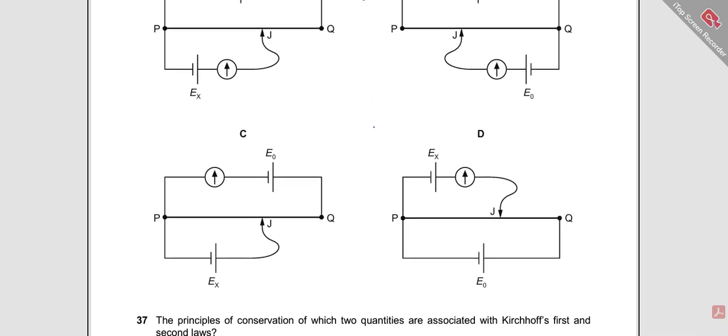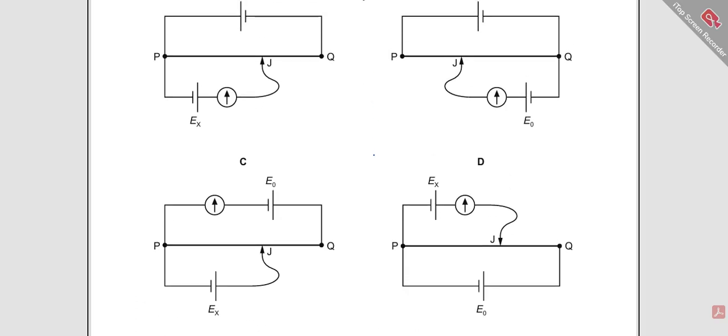So the end either has to be connected with both the positives, that is, the positives of the unknown and the known, or with both the negatives. This understanding of our potentiometer cancels this option because the end is connected to the positive of the source and the negative of the unknown. And it does not rule out any other possibility on this basis. Now, based on this understanding that it should be connected with the same poles, see, positive positive this might be an option, negative negative this might be an option, negative negative this might be an option.